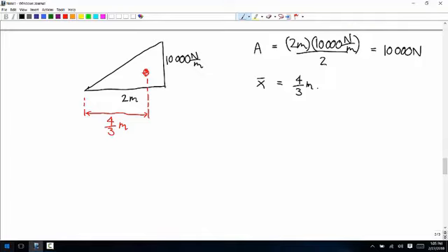Any questions about that? Yeah. That's right. Yep, that's exactly right. So just go to the table of shapes, and we're just calculating where the centroid is for a right triangle in this case. And it's always 1/3 of the way from the wall, 2/3 of the way from the point. Yes? Mm-hmm. Yes. Yep. You just add that as another force. Yep. We'll do some like that.